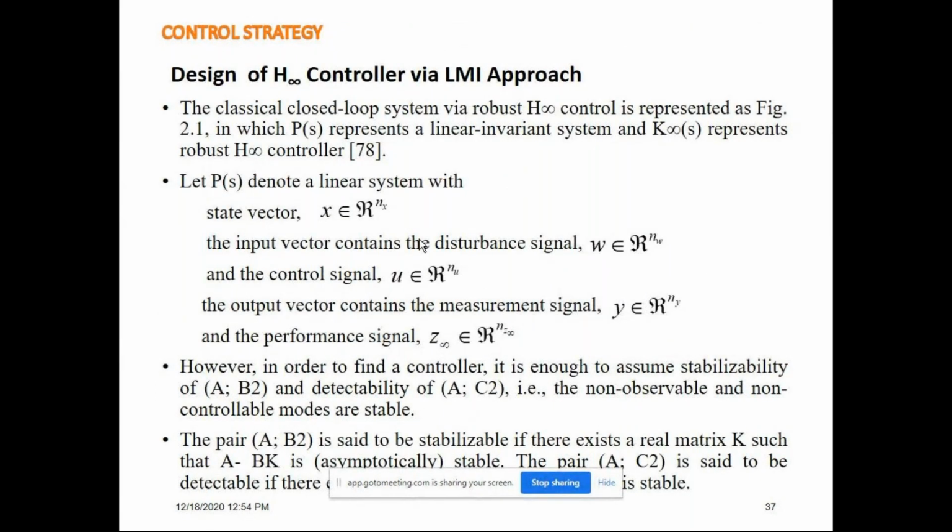So this is what I am telling: H infinity control using the LMI approach. Suddenly I came to this, how it is a discrete thing. Load frequency control, all of you are aware of. Your tie line, your predefined power exchange between area 1 and area 2, and your generation load mismatch. These two criteria have to be fulfilled, and accordingly your control from the primary and secondary action has to be made, and for the tertiary you have the economic dispatch.